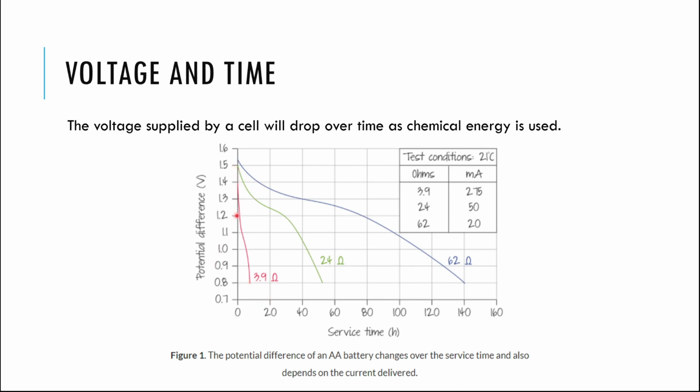All right, so number one, there's a certain capacity, and so I'm using more energy here if I'm pulling more current, so this is going to run out more quickly. But also, remember, the last unit is called the heating effect of electric currents. This battery is going to heat up, especially the more current I pull out. Remember, power depends on I squared R. So high current means I am going to have more significant heat loss in the battery, and because of that, it's even less efficient and will run out even more quickly when I'm pulling out large currents.